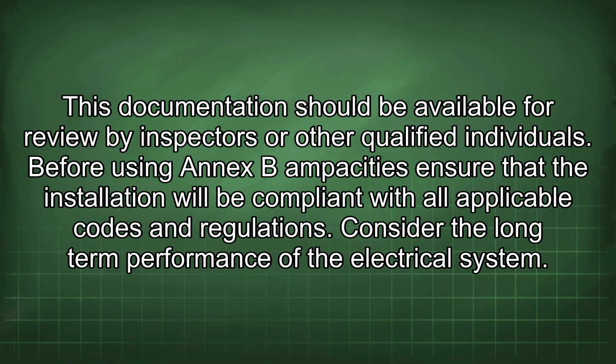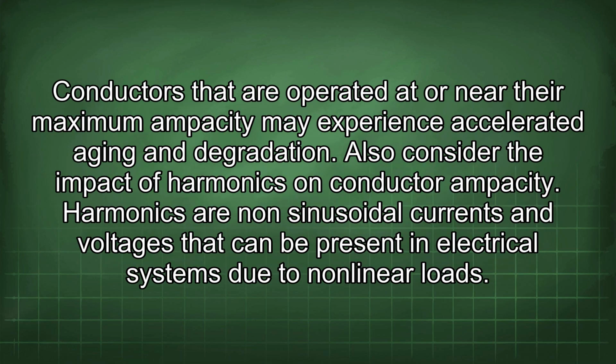Consider the long-term performance of the electrical system. Conductors that are operated at or near their maximum ampacity may experience accelerated aging and degradation. Also consider the impact of harmonics on conductor ampacity. Harmonics are non-sinusoidal currents and voltages that can be present in electrical systems due to nonlinear loads.